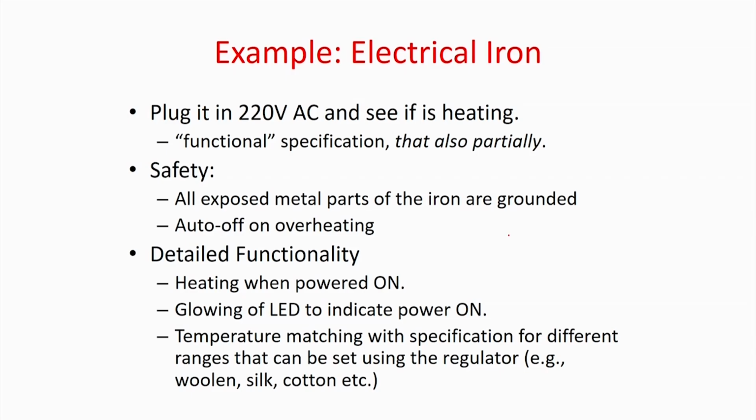I want to test it. So, we know that it is a very traditional system. Not many of the electric irons, I am talking about the very simple iron which we use in daily life, will have faults. So, basically what you do when we purchase it, we put it in a 220 volts AC source and see whether it is functionally proper or not, whether it is getting heated up or not. This is actually a testing part.